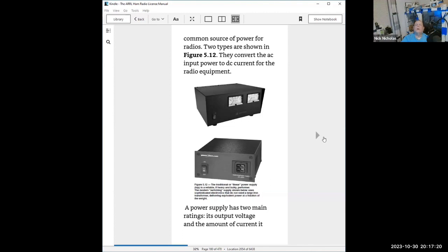So the advantage of a digital power supply, though, is that it doesn't have a great big huge giant transformer anywhere in it. They're much lighter in weight. They're usually smaller, more compact, and easier to carry around or move around. It's six and a half dozen of the other, one or the other, as to which one's a better choice. I tend to favor analog power supplies until I have to move them.